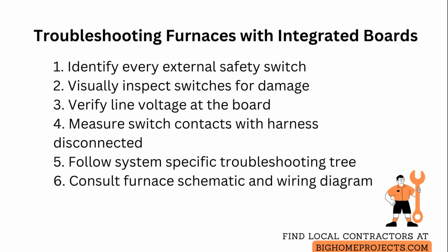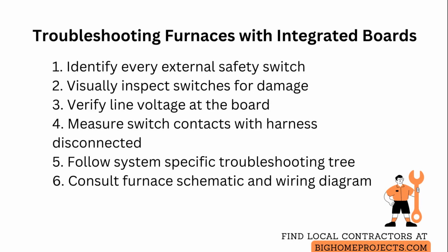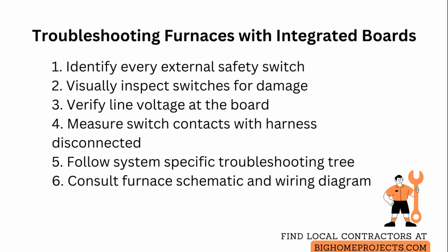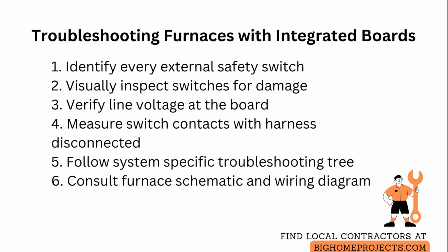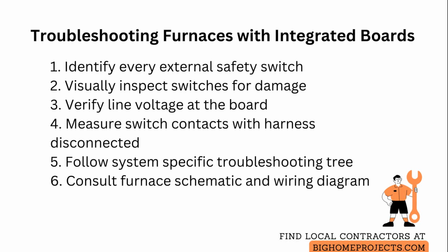Restore power and use a multimeter set to measure voltage to verify line voltage is present at the board and that the board is supplying the correct switched voltage to each external safety device while the furnace is in the appropriate operating mode. If a switch is open when it should be closed, isolate it by disconnecting its harness and measure across its terminals to confirm the switch contact state independent of board wiring.